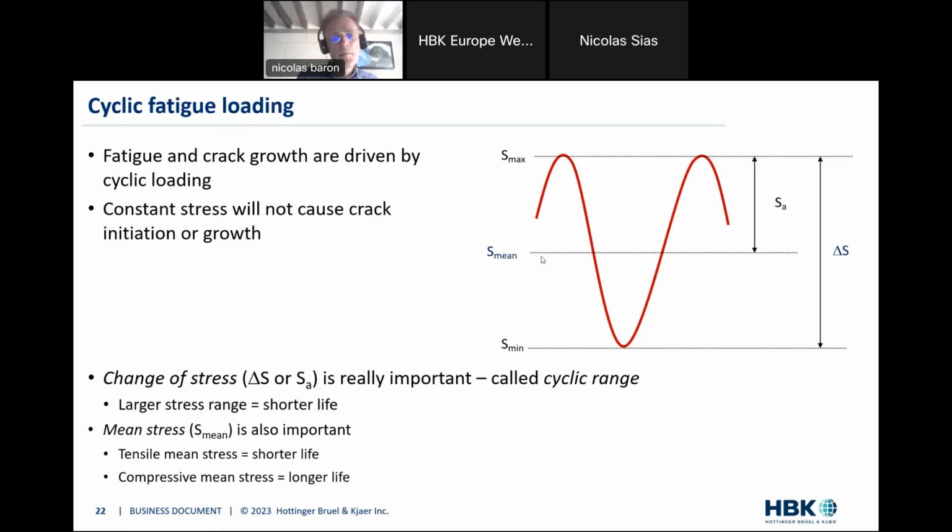That's why not only the cyclic range is important when it comes to fatigue calculations, but also the value of the average, the mean stress. So these two parameters are really to be taken into consideration for any calculation that regards fatigue phenomena.